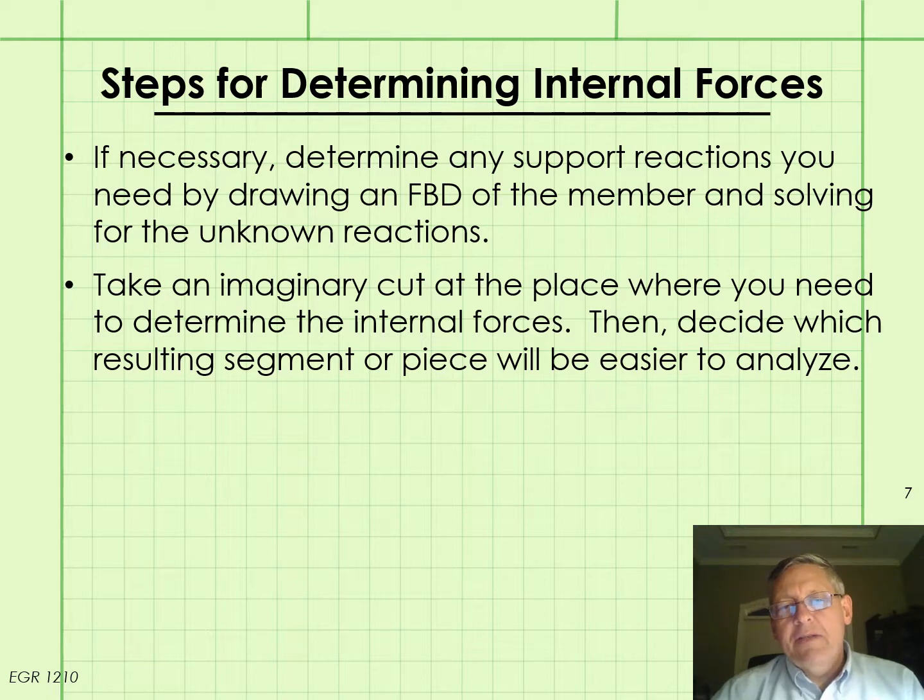Next, take an imaginary cut at the place where you need to determine the internal forces. Then decide which side of the cut will be easier to analyze. Very similar to what we did with method of sections in the analysis of simple trusses.